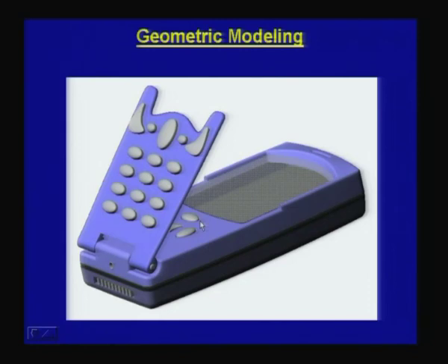So, what we are seeing here is only a visual representation of a geometric model, but internally it is stored as a mathematical model and hence available for various applications wherever the mathematical definition has to be used. For example, if somebody would like to know the weight of this particular product, one can easily get it, because you have the entire volume information which can be easily extracted from the geometric model or the mathematical model which is stored as a file.